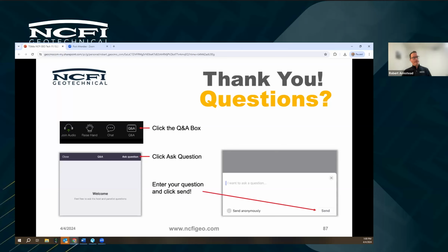Could you discuss possibly using dual component product for low pressure systems, 250 PSI? What would you recommend, if any? Slab jacking only. With the low pressure systems like the small cart systems that are out there, if they use a static mixer gun, then you don't want something that's too fast. 24044 is probably a really good system for that application. It's slow enough to work with the static gun, but fast enough to do good concrete lifting work.